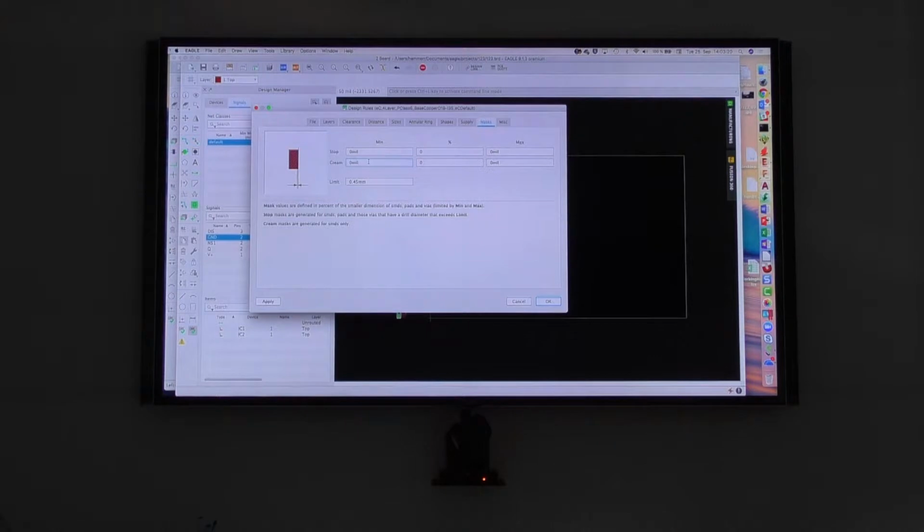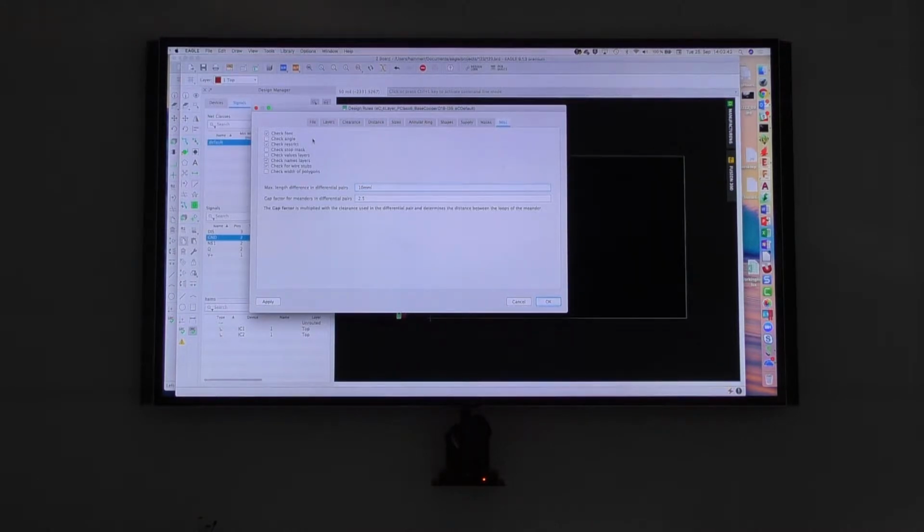That's something the design engineer has to decide on, or look into the data sheets of the manufacturers, because in most cases they tell you what area makes sense to cover with solder paste. Okay, then we have a number of design rule check options, check font, angle, restriction, and so on, so I can switch some of these checks on and off.